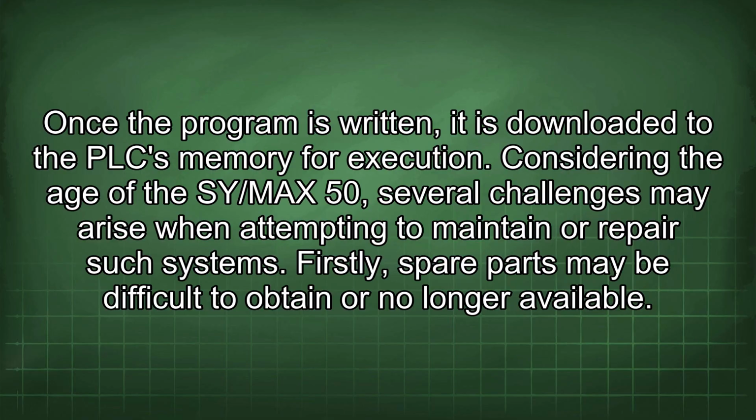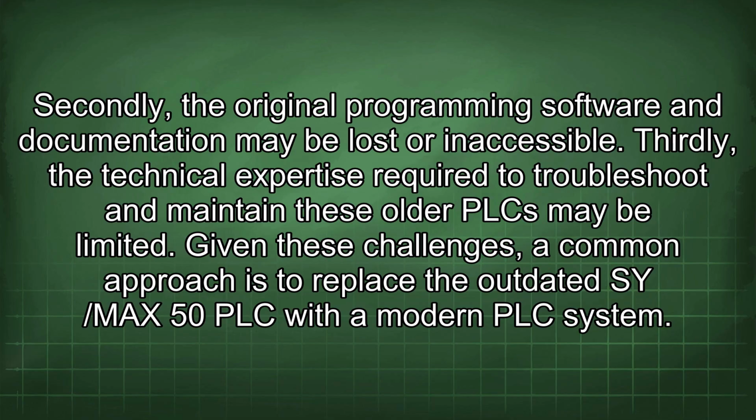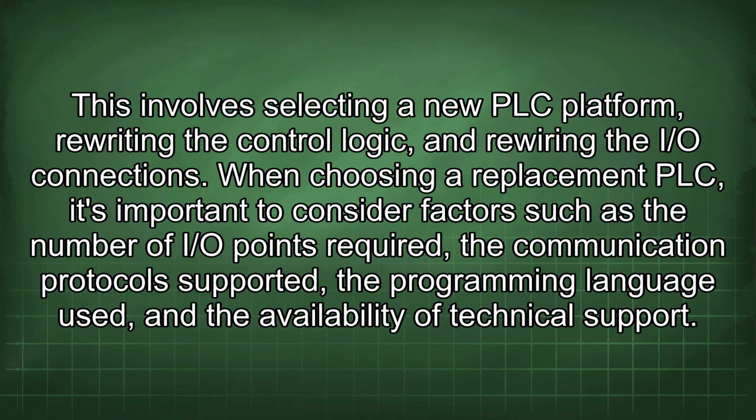Considering the age of the SY/MAX50, several challenges may arise when attempting to maintain or repair such systems. Firstly, spare parts may be difficult to obtain or no longer available. Secondly, the original programming software and documentation may be lost or inaccessible. Thirdly, the technical expertise required to troubleshoot and maintain these older PLCs may be limited. Given these challenges, a common approach is to replace the outdated SY/MAX50 PLC with a modern PLC system. This involves selecting a new PLC platform, rewriting the control logic, and rewiring the I/O connections.